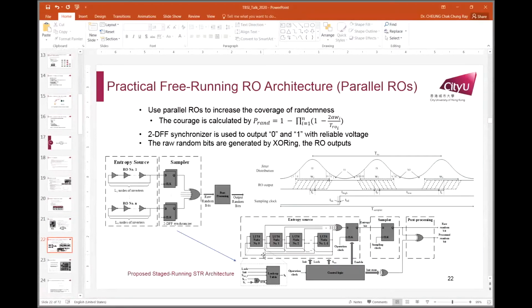When we talk about the root of trust, we start from the fundamental building block inside the chip, which is the flip-flops, the LUTs, and so on. So here is a typical source of randomness. Where does it come from? Imagine this is a typical ring oscillator. There's a ring, and the data keeps on switching. Later, you do some sampling, you get the data, and eventually you get the final bit. You want to collect the data with a processor, and eventually you get a random bit. We are able to observe the waveform and capture all the different glitches and uncertainty, what we call the metadata. This is what we call the free-running ring oscillator.